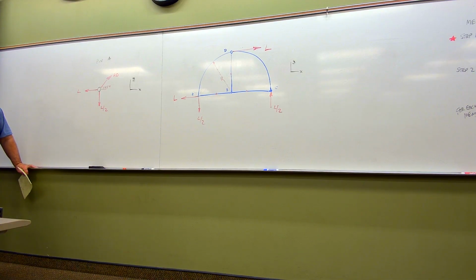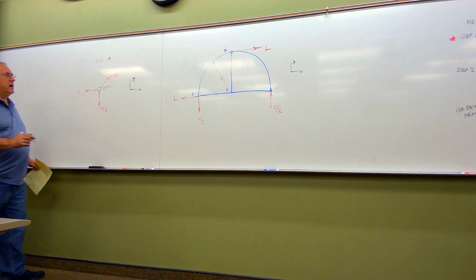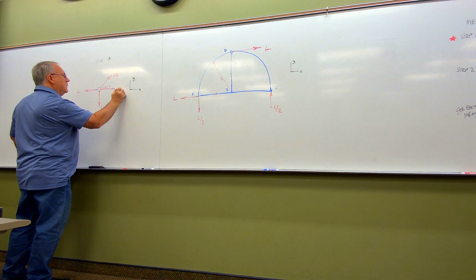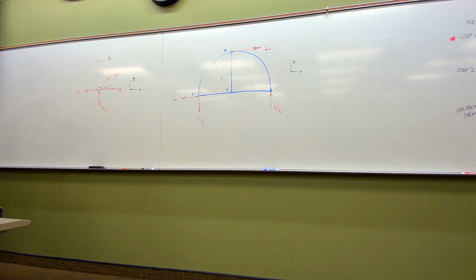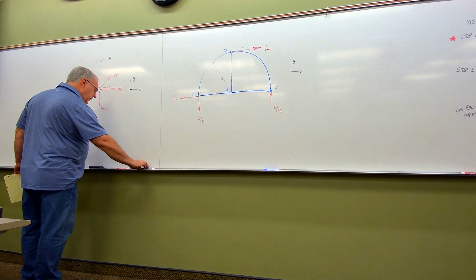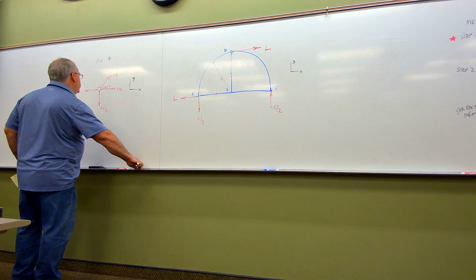And I'm almost done. I haven't contemplated AB, so I got AD, now I got AB here. Again, arrow drawn away, assumes tension. So now my free body is done. 2 unknowns. Let's do the equations of equilibrium here.